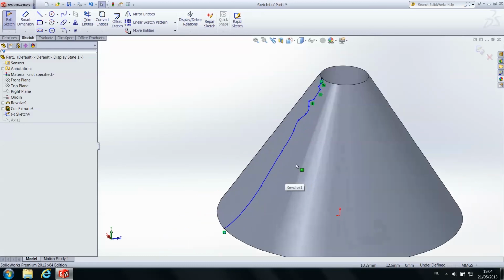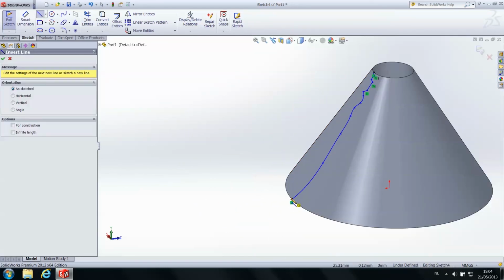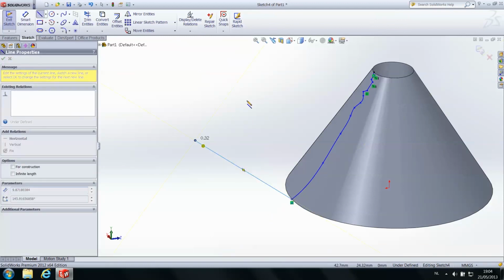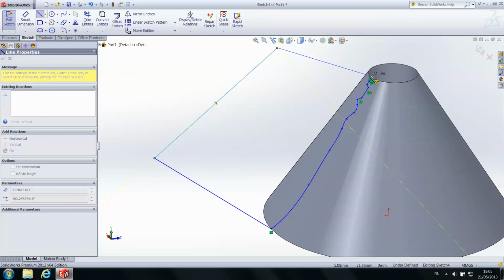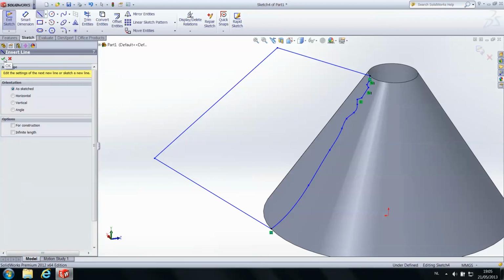It always has to be 360 degrees closed. Here we see that this point and this point aren't connected. So we just go like this. You put it over here, over here, over here, no biggie, and then you connect it with the beginning point. And now we have a completely closed sketch, and now we can work properly.